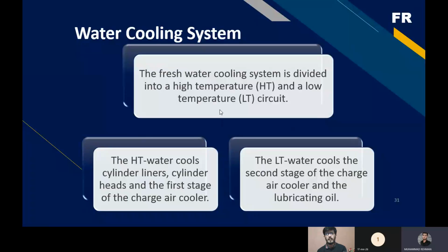So first, let's see the high temperature water. High temperature water cools the cylinder liners, cylinder head, and the first stage of the charge air cooler. On the other hand, the low temperature water cools the second stage of the charge air cooler and the lubricating oil.